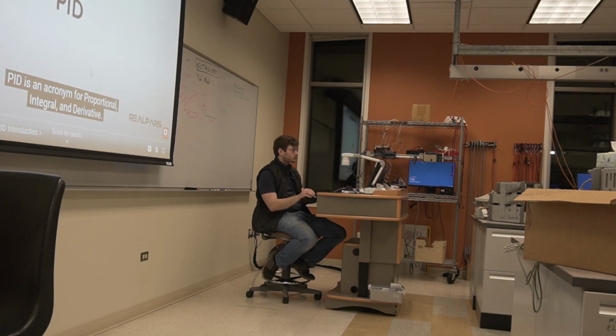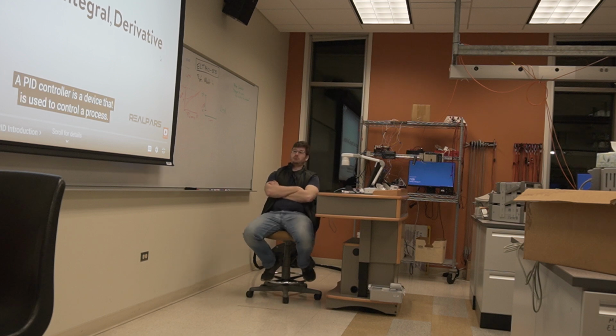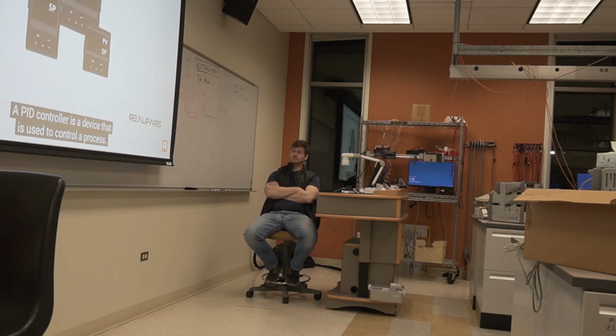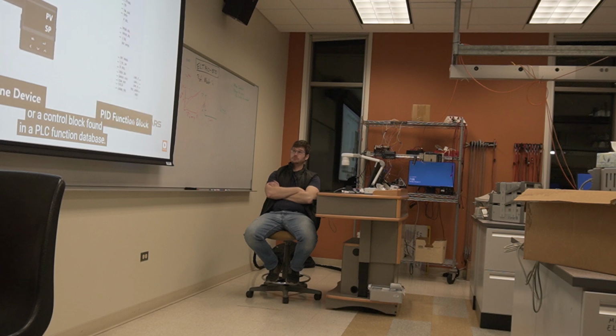PID is an acronym for proportional, integral, and derivative. The controller is a device that is used to control a process. The controller can be a physical standalone device, or a control block found in a PLC function database. The PID portion of the controller is a series of numbers that are used as adjustments in order to achieve your objective.